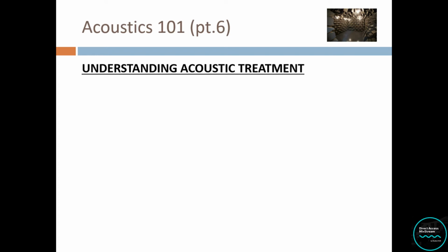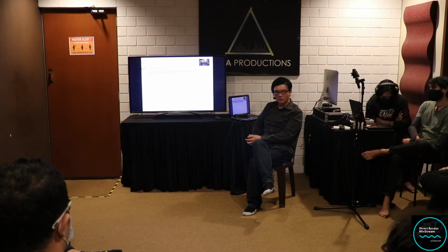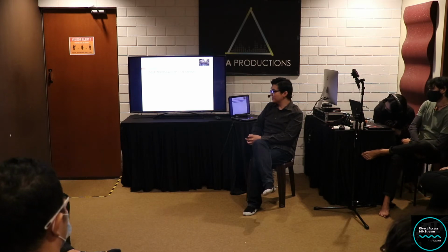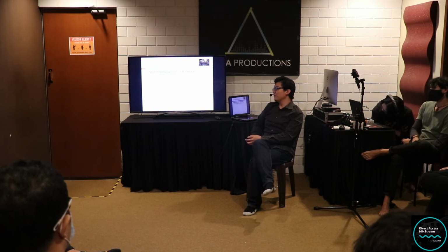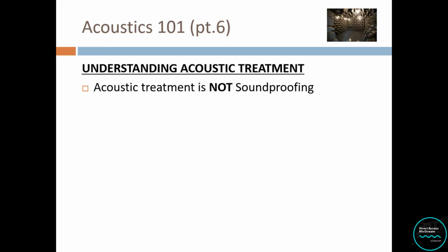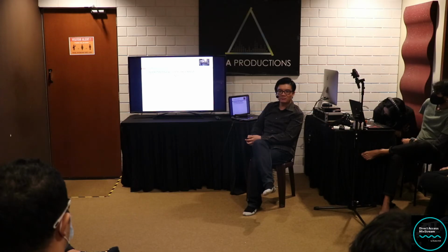Understanding acoustic treatment. Very important. First point, if you can't remember all the other details, remember this: acoustic treatment is not soundproofing. If you go online, to Shopee, Lazada, you see soundproof foam, soundproof this, soundproof that. I can tell you immediately, if they use those terms, first of all, they don't know what product they're selling lah.